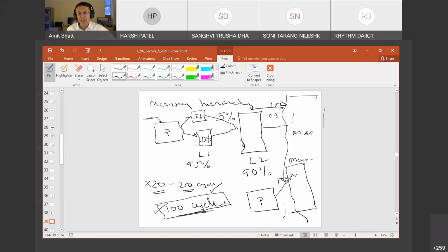So it has just one memory, and this is called TCM, or tightly coupled memory. So it's just one memory, and access time is fixed. And small processors like ARM7 or ARM9, which you're using, do not have an expensive thing like this, because this is an overkill for a small processor. So small processors are by necessity of this type.